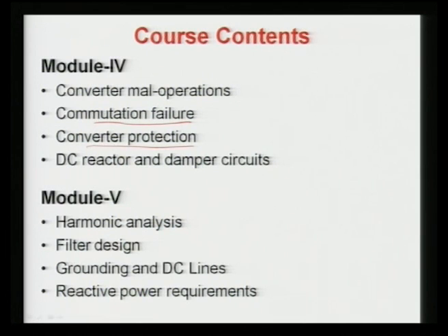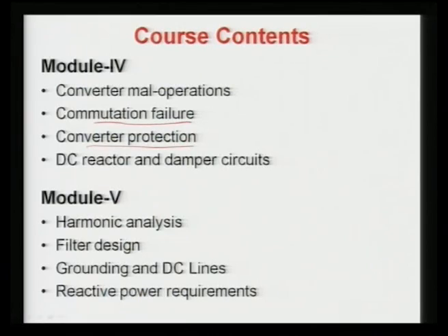Then we will see how to protect the overall converter circuit. We want to protect the converter circuit and we want to protect our HVDC lines. So, we are going for overvoltage protection, overcurrent protection similar to AC, and also differential protection for checking the link differential current. So, the complete inverter as well as rectifier side system protection is discussed.